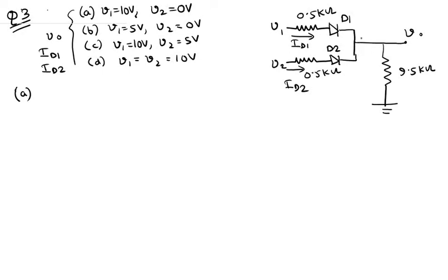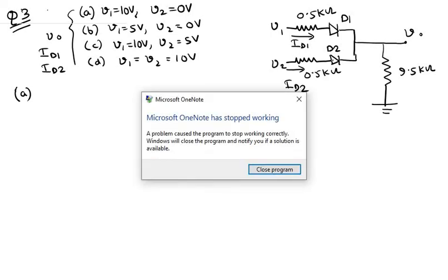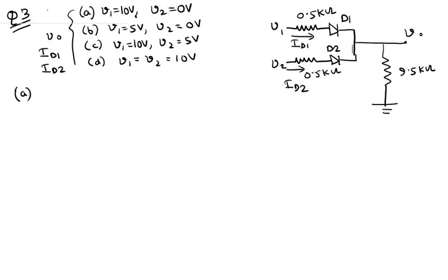Now if the voltage at this point is somewhere between 10 volts and 0 volts, then this diode D2 is basically reverse biased. So no current would actually flow through this diode D2 because this is already reverse biased. Okay, now let us call this current IR.